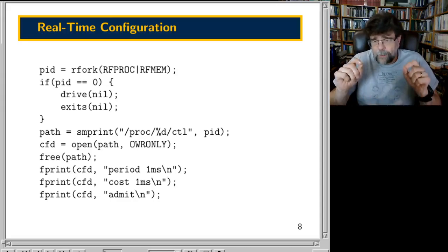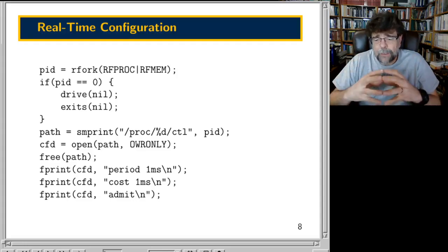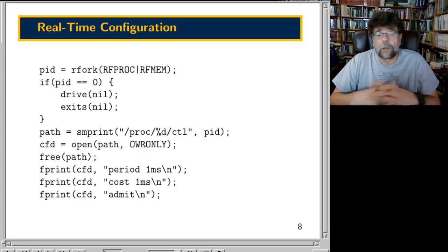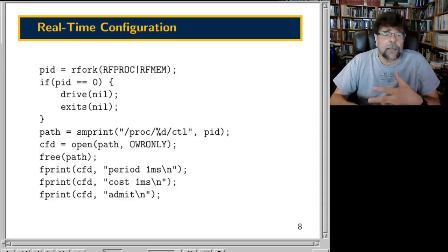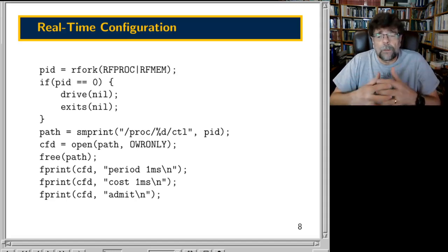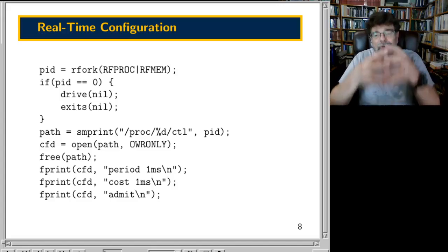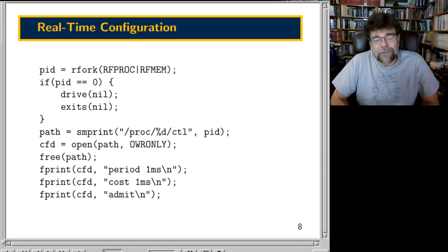And I should mention, by the way, that the rate at which we're updating is somewhat critical. My original thought had been, if I can update the screen 30 times a second, that should be good enough. After all, movie film classically was 24 frames a second. NTSC television, each half of the interlacing was a 60th of a second, so the full frame was done every 30th of a second.